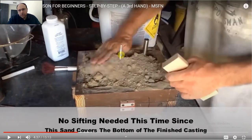So this thin tube, he's putting it just to form a vent. As he mentioned, this vent is known as the riser. In some cases, in some bigger castings, we could use this riser as a feeder to keep on feeding the melt during the shrinkage process. But anyway, all of these details, definitely you're gonna study them in the manufacturing process class.